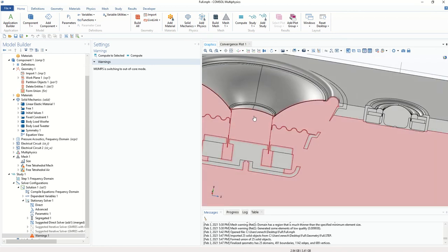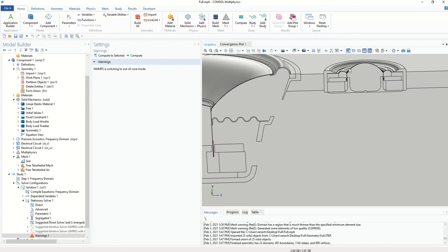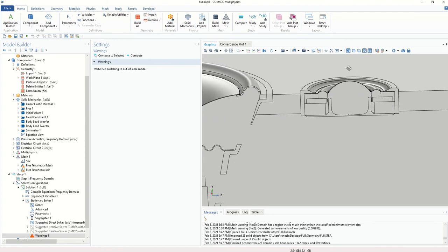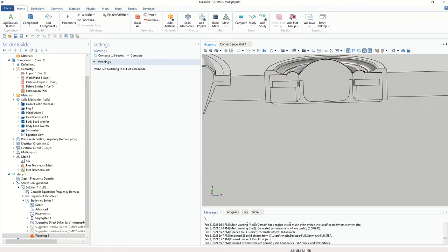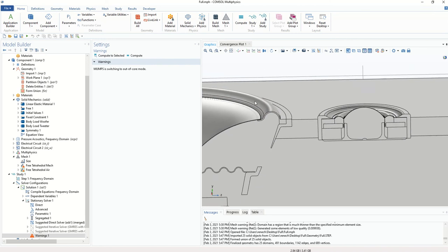So what you need to do now is to figure out your material properties, which can be extremely difficult. So for each of these parts here, you need to know what is my stiffness, what's my Young's modulus, what's the density, that's fairly easy to figure out, and what's the Poisson ratio. And also you need to know for a lot of the materials, what is the damping. So we have these 4 parameters for each part that you need to know.